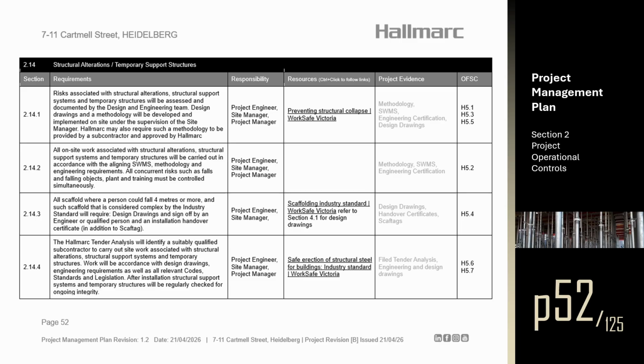Section 2.14.4. The Hallmarc tender analysis will identify a suitably qualified subcontractor to carry out site work associated with structural alterations, structural support systems, and temporary structures. Work will be in accordance with design drawings, engineering requirements, as well as all relevant codes, standards, and legislation. After installation, structural support systems and temporary structures will be regularly checked for ongoing integrity.